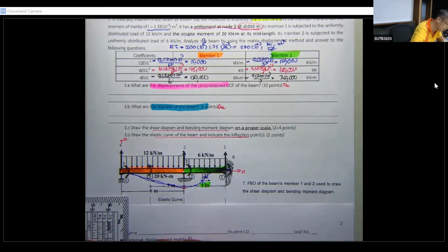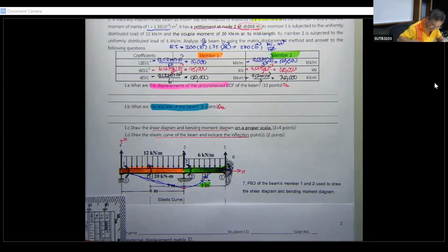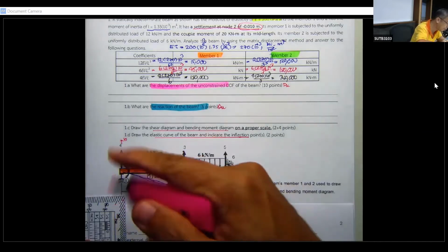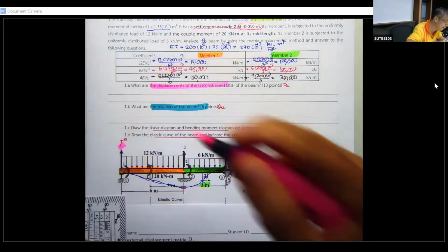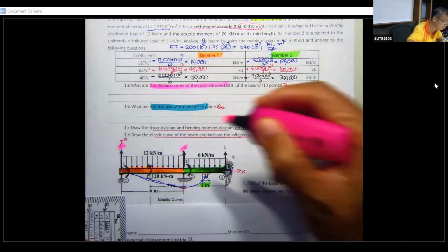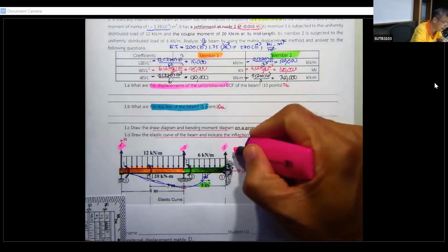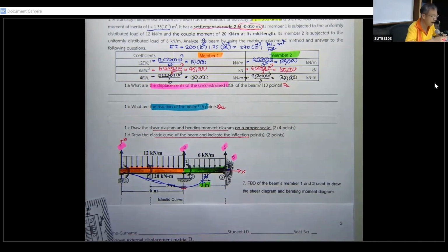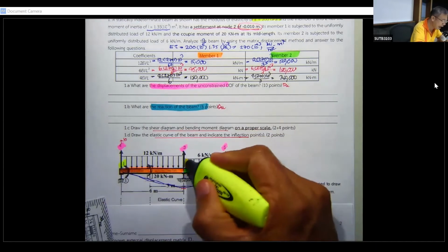And let me move the D sub K over here because I require to work on it. For the D sub K here, we have what? The degree of freedom must be classified into the constraint and unconstrained. You can see the degree of freedom constraint at the support is a roller, so constraint over here is a roller, constraint over here is fixed. So we will have only two unconstrained degrees of freedom, D1 and D2.